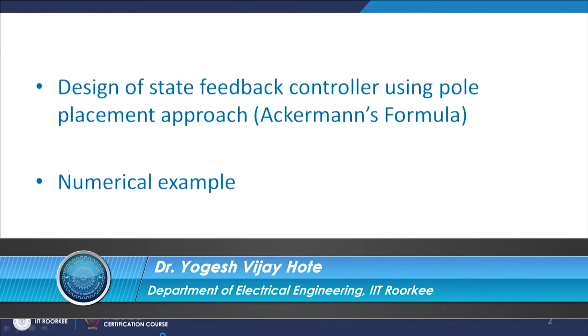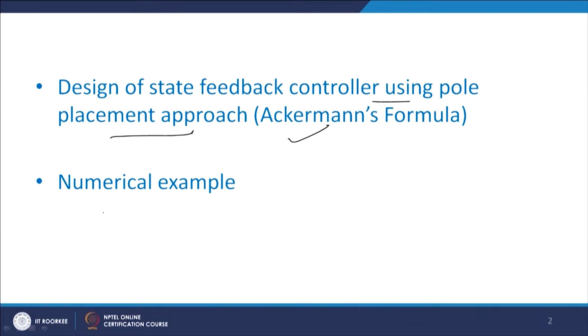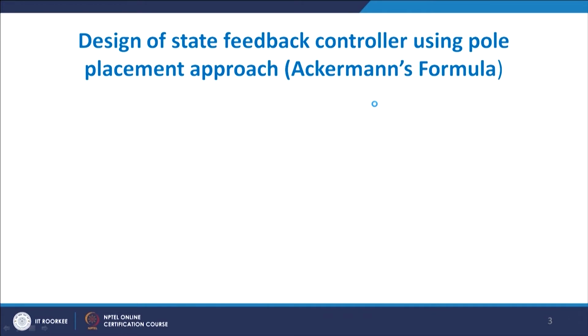Start with the pole placement by state feedback part 3. In this we will study design of state feedback controller using pole placement approach, that is Ackermann's formula, and whatever technique we will study that is based on Ackermann formula, that means we will solve a numerical example based on this Ackermann's formula.